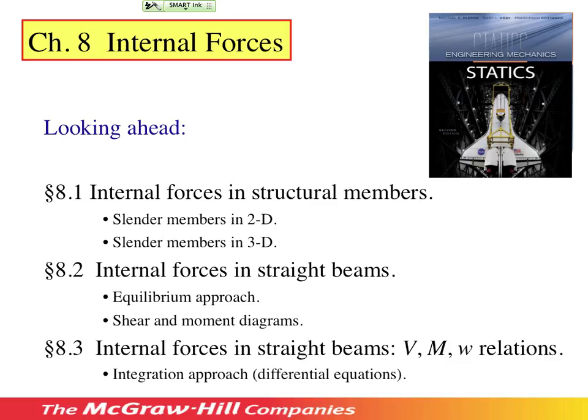Instead, our interest will be in developing expressions for internal loads as a continuous function of position as we move from one side of the member to the other. Having such information is crucial when we make the transition from rigid to deformable bodies. Internal loads as a continuous function of position are one important input to understanding how members deform under load.